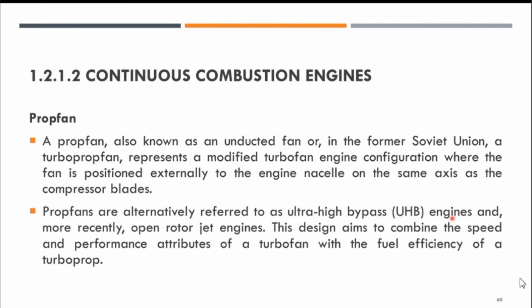So ultra bypass. You have a bypass engine, and this one is ultra high bypass, meaning that the majority of the air flow goes external to the engine instead of through the core of the engine. More recently we call it an open rotor jet engine. This design aims to combine the speed and performance attributes of a turbofan with the fuel efficiency of a turboprop.